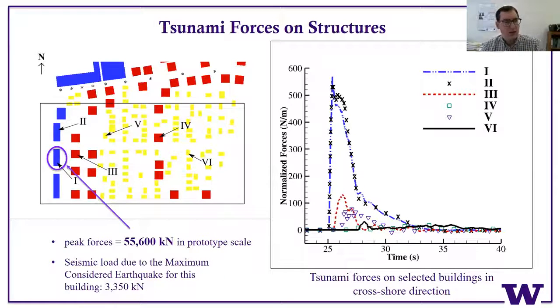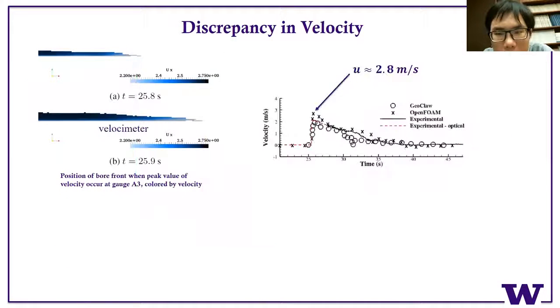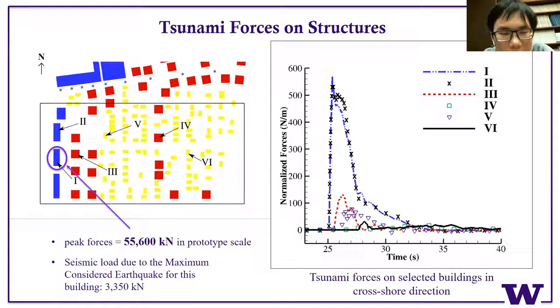Okay. The boundary conditions you used in the video, it seemed to show that you had reflective boundaries. Is that the case? Yeah. So the boundary on the left is an inlet boundary, and all three other boundaries are walls. So you can expect the wave will get reflected when it hits the wall.